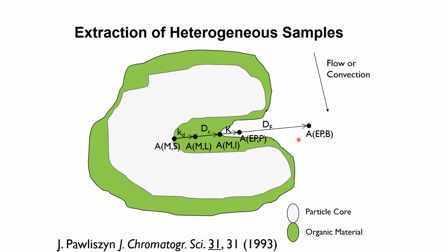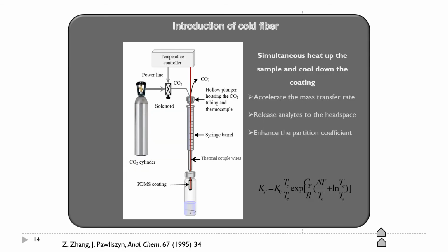And if you look carefully at these fundamentals, which I developed in this paper, you'll notice that the temperature plays an important role. Increasing the temperature allows us to increase the rate of extraction. So that's why we eventually proposed superheated fluid extraction based on high temperatures, which was also used as a high temperature extraction method. You can also use those principles in designing high temperature desorption in the